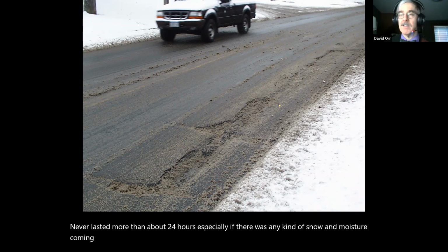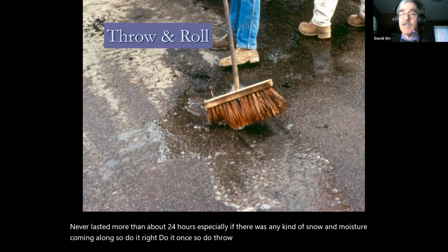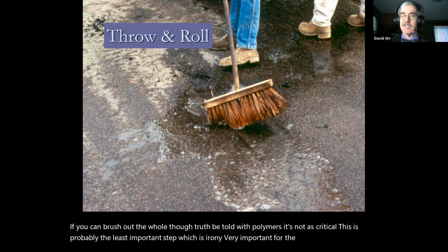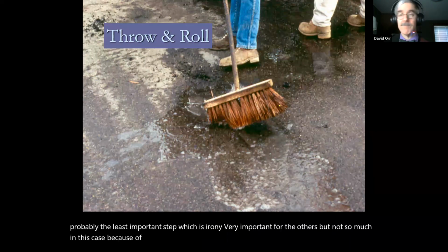So do it right, do it once. So do throw and roll. I'm a big fan of it. You got to go in first. If you can, brush out the hole. Though truth be told, with polymers, it's not as critical. This is probably the least important step, which is irony. Very important for the others, but not so much in this case because of the polymers, but they cost more.